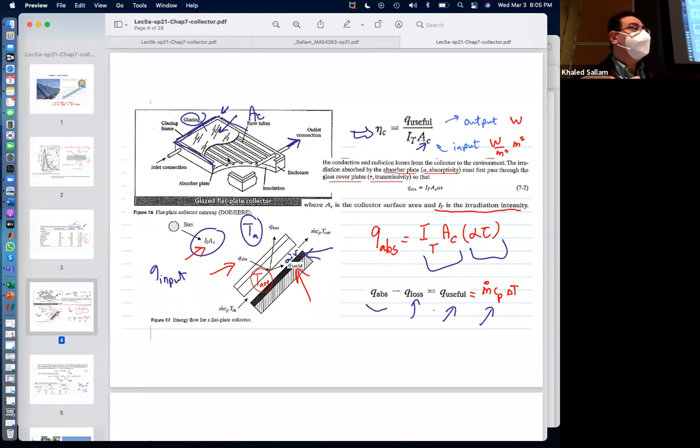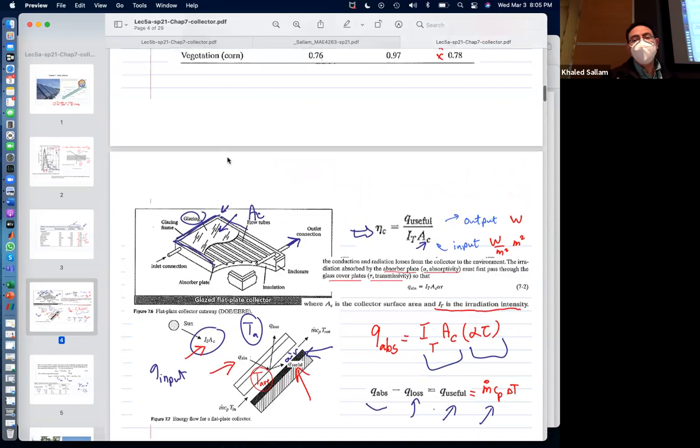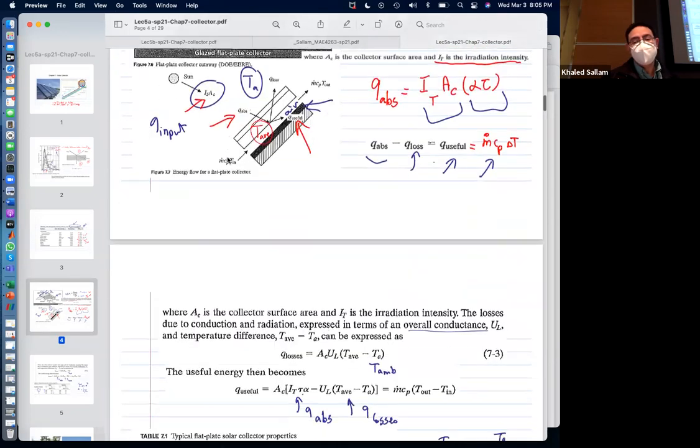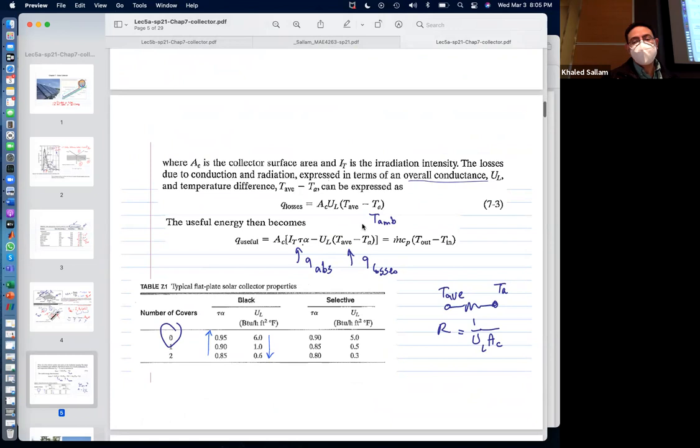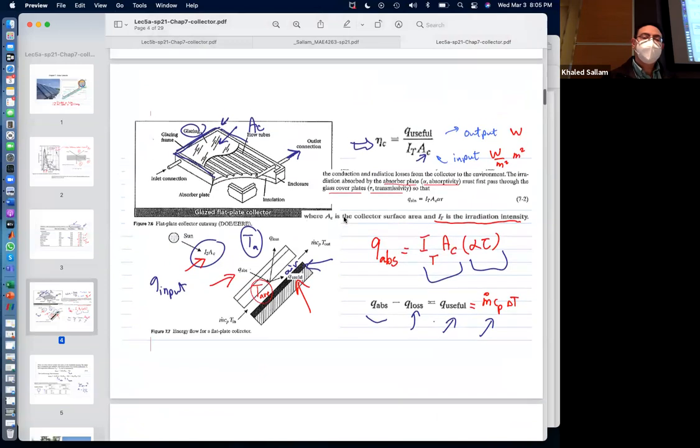So in there, the house and the outside, huge temperature difference across. So the wall needs to be really thick. The insulation needs to be really huge. Otherwise, the heat will just really run outside, right? So the Q loss is dependent on that temperature difference: T inside minus T outside. Outside is T ambient. Inside there are actually 2 temperatures. What are the 2 temperatures inside? T water in, T water out. The water comes cold and the water leaves hot.